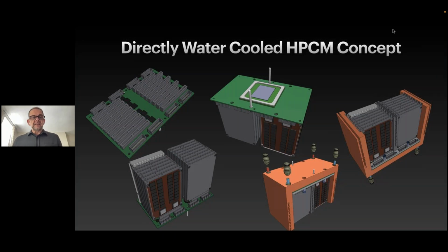So effectively, what we've got here is, I'm hoping you're all familiar with the OAM, the OCP accelerator module. And that is very similar to NVIDIA's proprietary SXM module that they use for all of their GPUs in the data center. So it's this mezzanine module format, and the size is roughly 6 inches by 4 inches. That then will house a very powerful processor, up to 1 kilowatt these days. I think the H100 is mentioned as being around 700 watts. But the latest OAM V2, I believe, is trying to support 1 kilowatt.